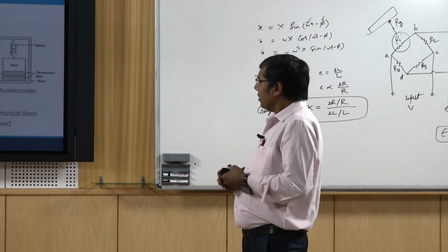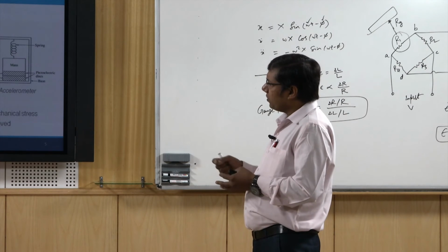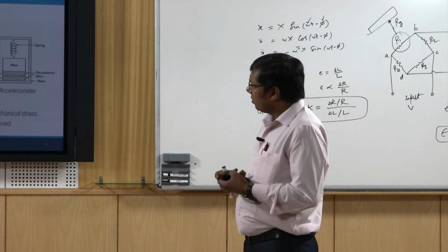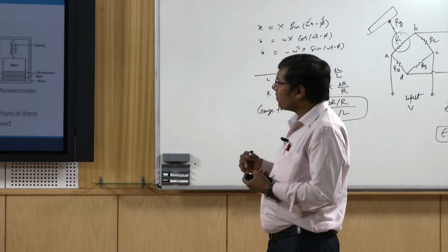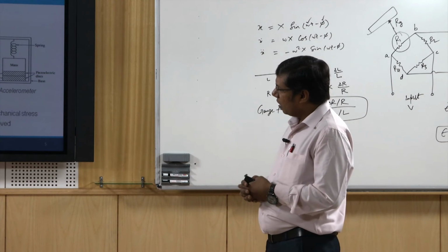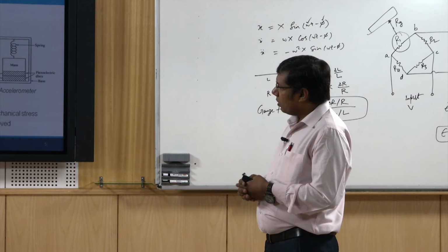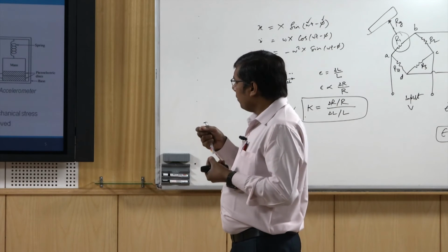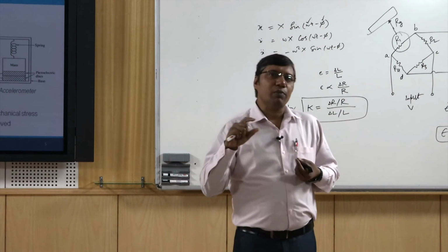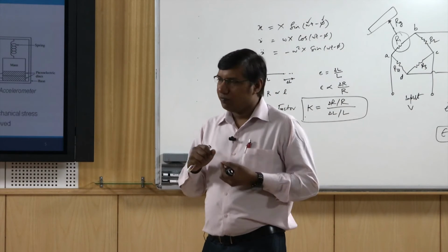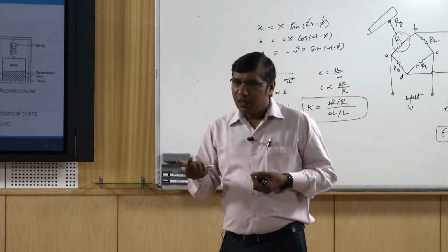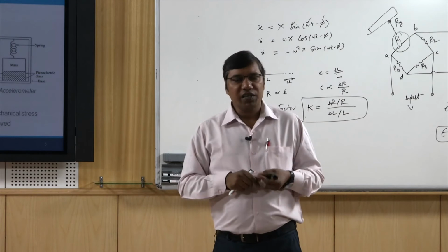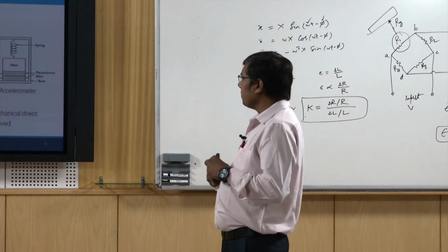Here we can see a plate of piezoelectric material with thickness T, and there is some force applied on the surface in the X direction, perpendicular to the surface. If we connect the two surfaces, we can know the voltage developed on the surface due to the application of that force, and by measurement of that voltage, we can know the force or displacement applied on the surface.